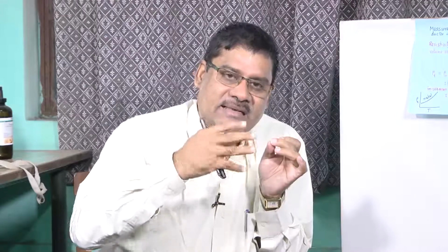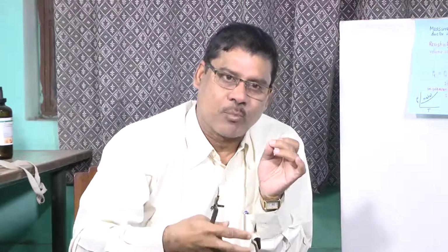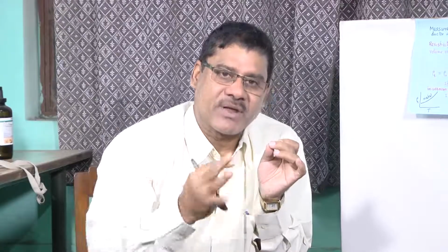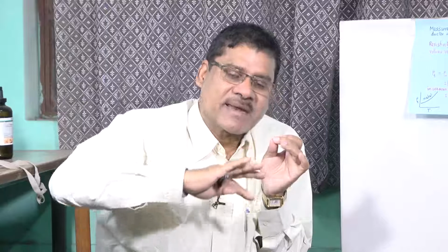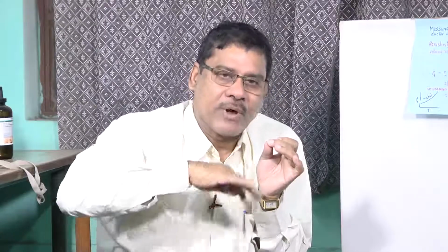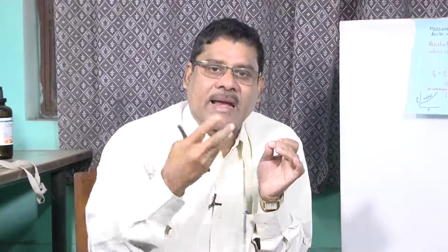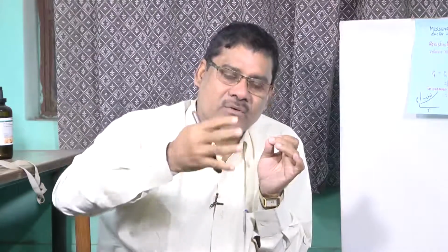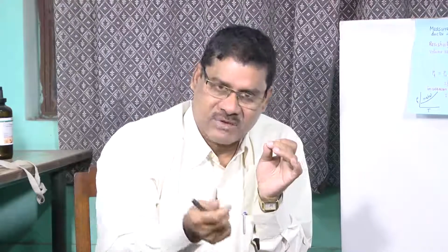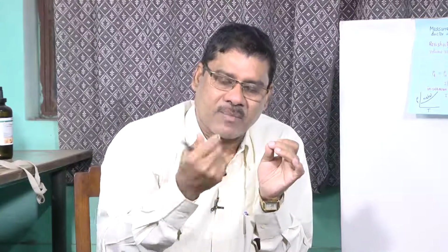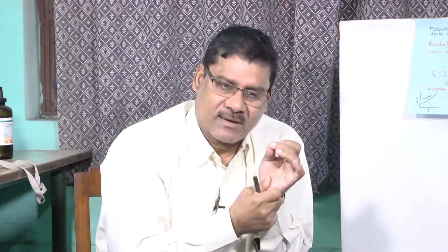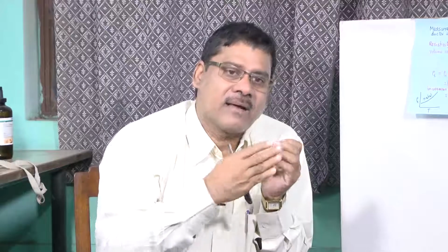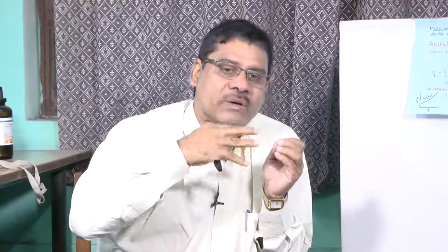Okay. And this lattice vibration becomes prominent, or it changes with the temperature. So, scattering will be higher and higher when temperature is higher and higher, because you will get a higher number of phonons from the lattice vibration, and there will be more scattering and there will be more resistance.